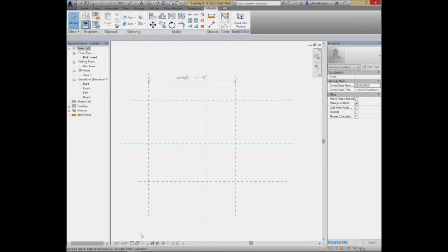It's kind of moving around. It's stretching one side or the other. I'd really like to be locking that as the center point. And to do that, we're going to add another kind of constraint or another dimension to it that'll create that behavior. So how that works is we'll say annotate.